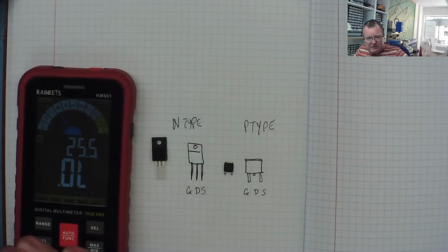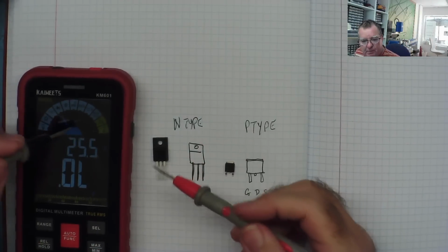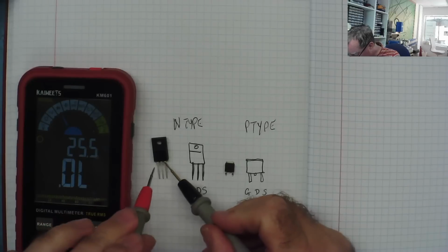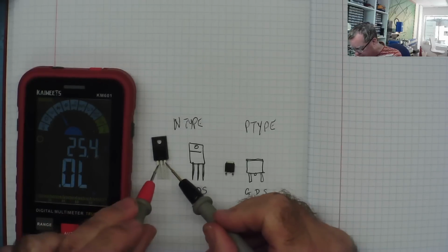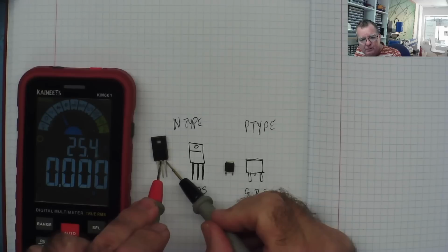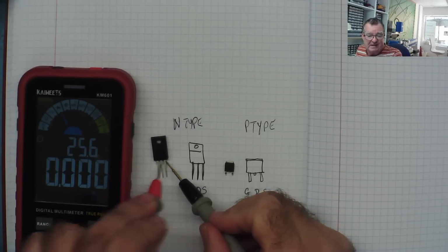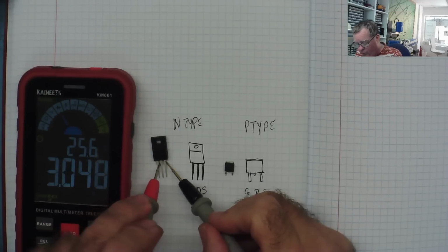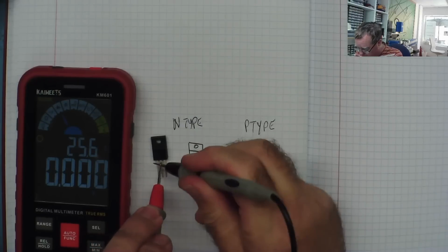So we can see why the transistor turns on, because we apply a positive voltage to the gate compared to the source. Positive to the gate and it turns on. The question is now, why does it stay turned on? Why does it not only turn on when there's positive voltage on the gate? Because there isn't any now. I've taken the meter off, there's no positive voltage on the gate. Why is it still switched on? Until we put the negative on the gate.